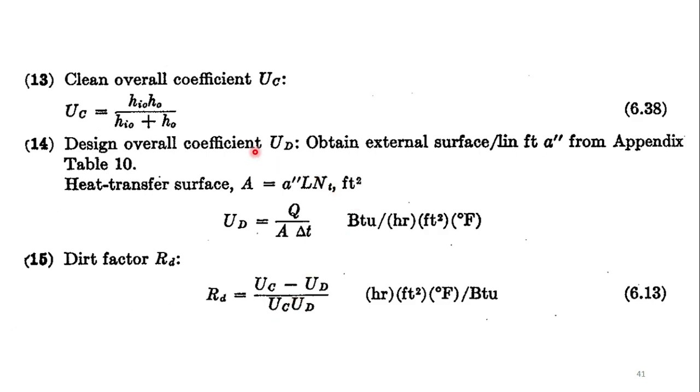And then you have to determine the clean overall coefficient, design overall coefficient, and then ultimately you have to determine the surface area, the heat transfer surface area, depending upon this clean overall and the design overall coefficient, and ultimately you have to determine the dirt factor.